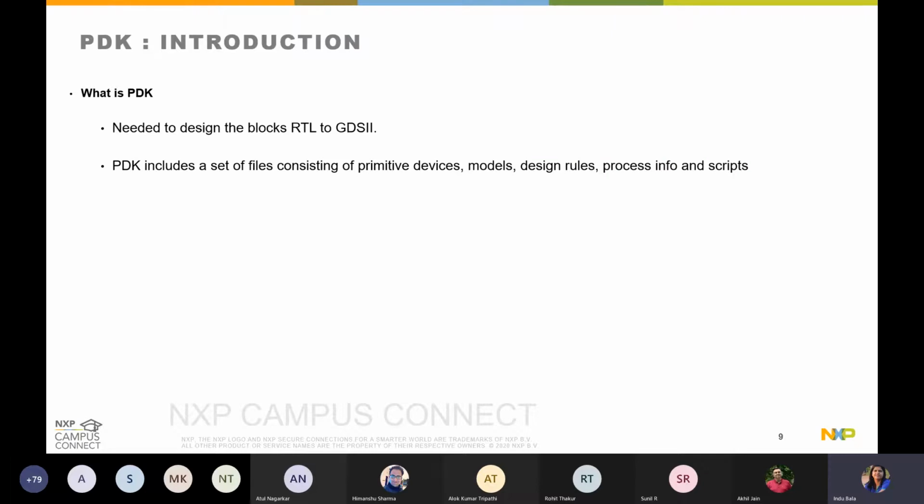We have the SPICE models, which are provided by the foundry. We have design rules, different kinds of design rules: DRCs, DFM. We have ESD-specific rules. We have latch-up rules. We'll go into more details about these in the next slides.